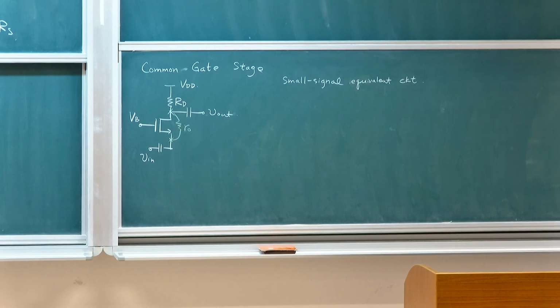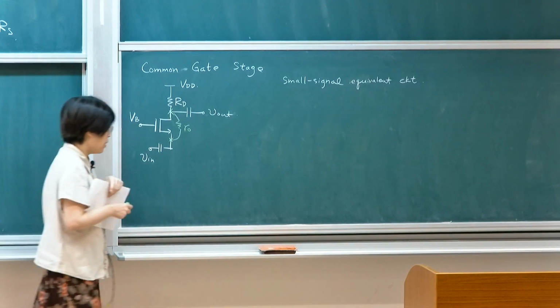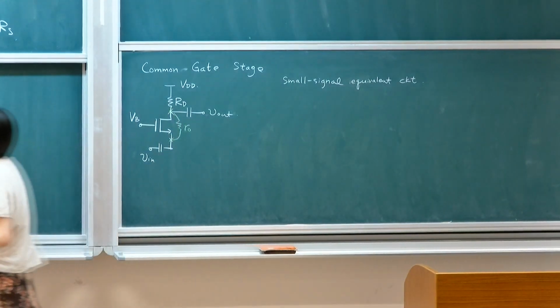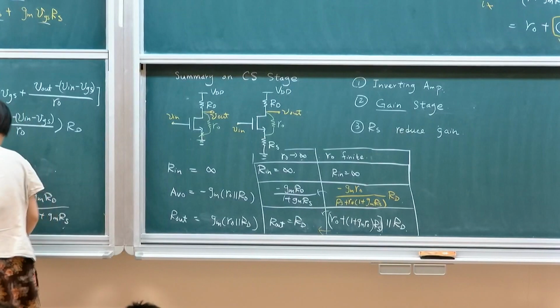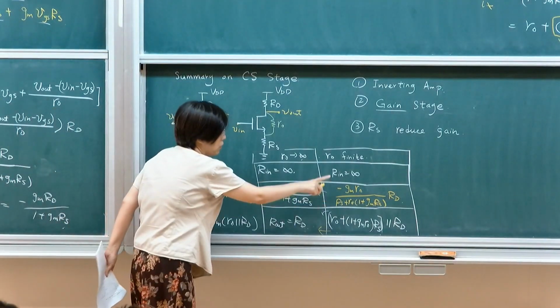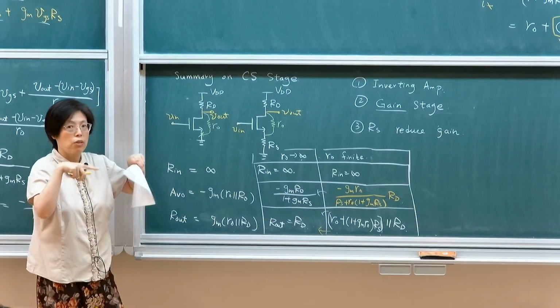Therefore, it's much easier. So you will see complication only in the degenerated source circuit and the common gate scenario. Okay, so you would then need to analyze it in separate ways, otherwise it will lead to these kinds of complications when both terminals are not grounded.